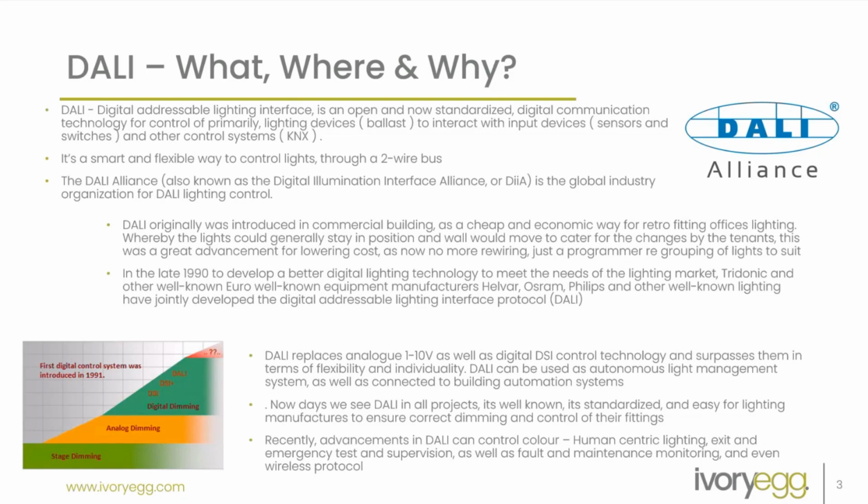Now it wasn't completely open. Since then, Dali produced the Dali Working Group, and now that's transformed into the Dali Alliance. What they've done, which is really important, is standardize the Dali protocol, which truly means that you can have anyone's fittings with anyone's sensors, with anyone's gateways. Dali was there to replace 0 to 10 and 1 to 10, and also DSI technology. Nowadays, Dali's in a lot of projects. It's well known, it's standardized. It's easy for lighting manufacturers to ensure correct dimming and control of their fittings.